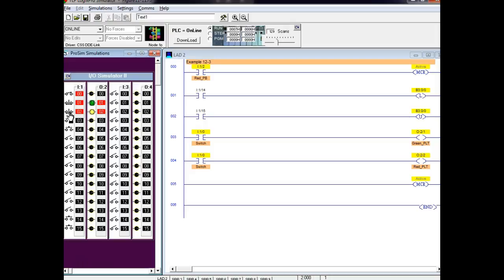Whoever wrote this, I said he, I guess, who wrote this? Rockwell, Max Rabie, R-A-B-I-E, made the same mistake that we try to make for motor control. If it says we're using a normally closed contact, then by George, we think we have to use a normally closed symbol. But this is not a relay, it's what the PLC sees as true and what it sees as false. So examine closed, the PLC sees a 1 as true, and examine off, it sees a 0 as true.